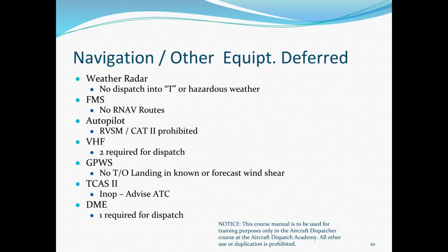So, I get a lot of MELs for passenger seat reclining or passenger tray table or cabin trim, stuff like that. Those kind of MELs or NEFs, we just don't even worry about. It just doesn't affect the aircraft. It's more there for information than it is for we have to do something about it.